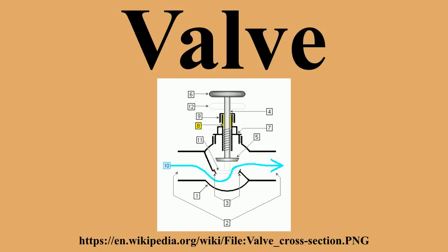Ports. Ports are passages that allow fluid to pass through the valve. Ports are obstructed by the valve member disc to control flow. The valves most commonly have 2 ports, but may have as many as 20. The valve is almost always connected at its ports to pipes or other components. Connection methods include threadings, compression fittings, glue, cement, flanges, or welding.